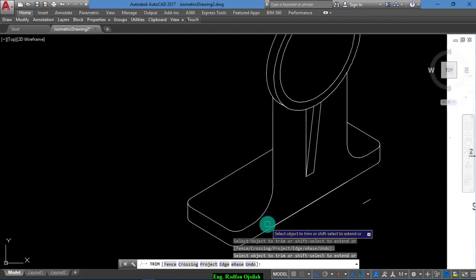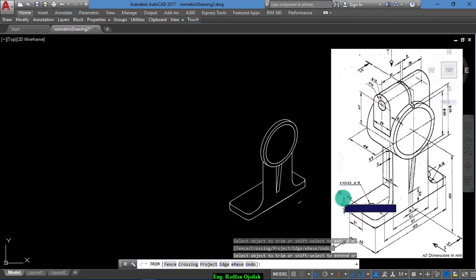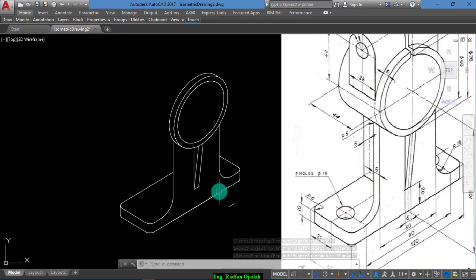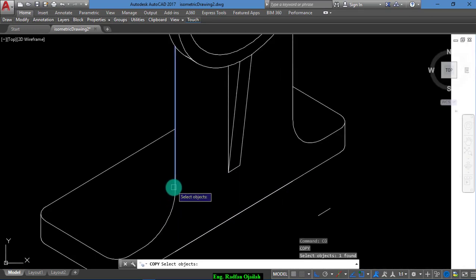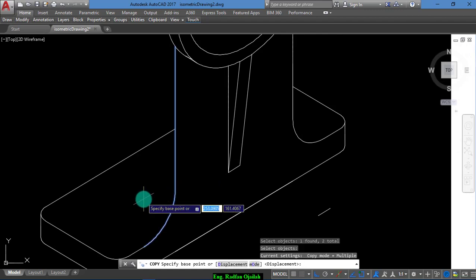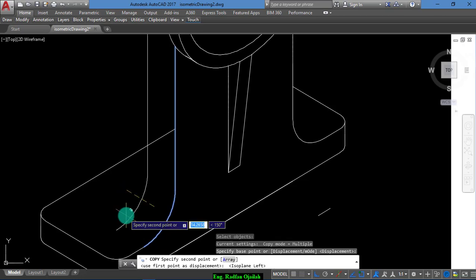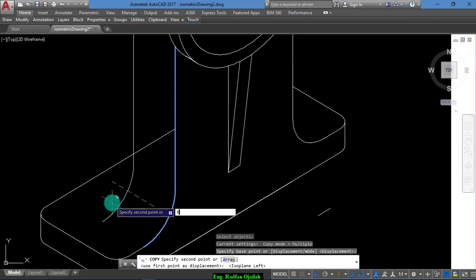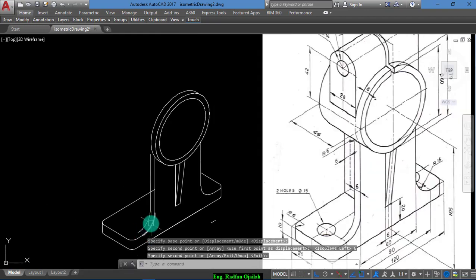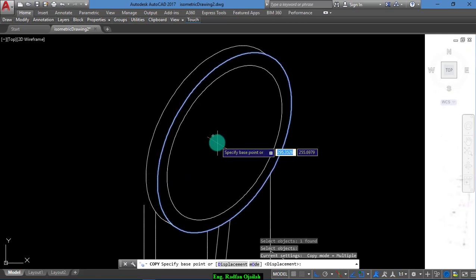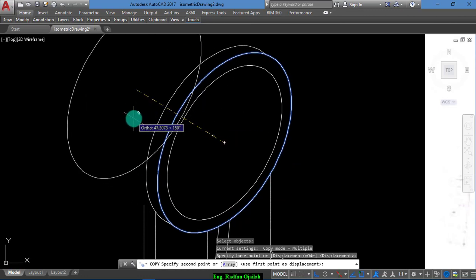Okay, now we are done with this portion. Now this line has an offset of 6, so we copy this line and this arc a distance, but before that write F5, a distance of 6. Okay, copy this outer one from the outer center, a distance of 44.